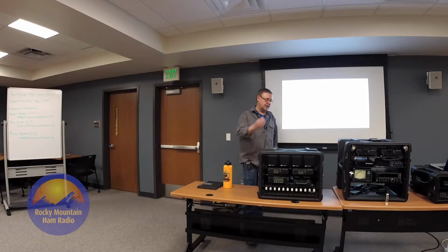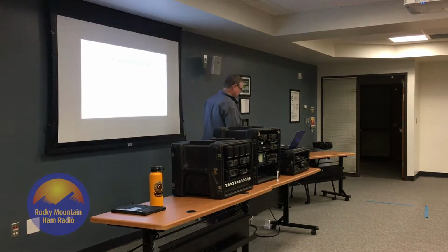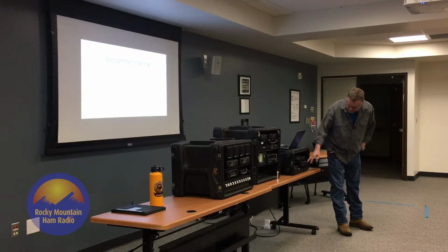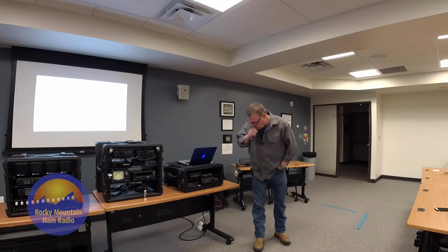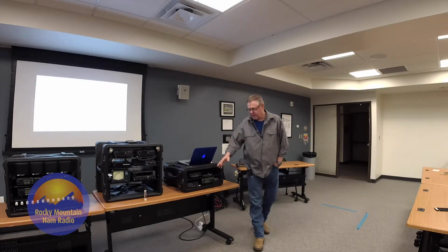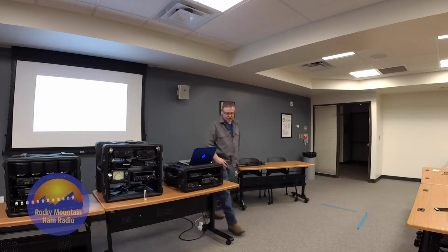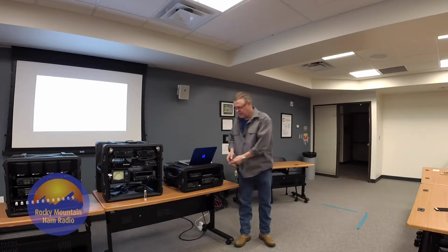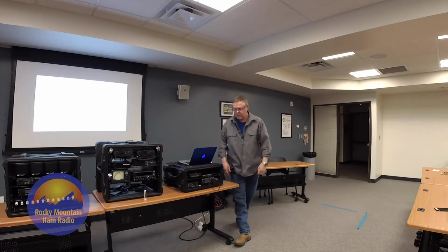But power supplies, the next thing I guess we'll touch on for a moment is how are you going to power these things and interface it all. This one right here and this one right here, all the interfacing is done inside, and I can switch here to any of the data modes. This is hardwired to my TNC. Everything's hardwired here. This cable actually comes out and goes to my computer, my laptop, so I can interface the data modes.